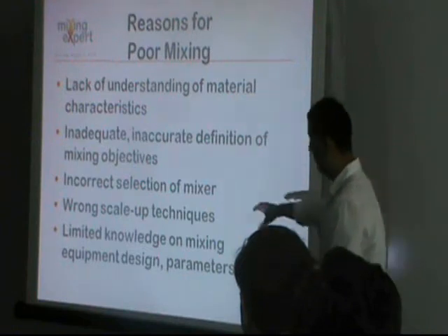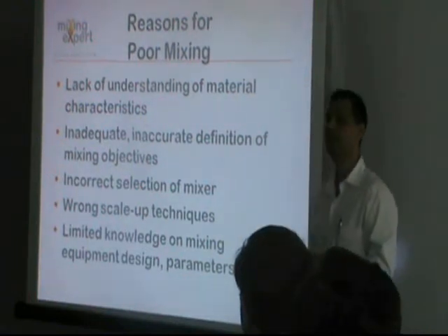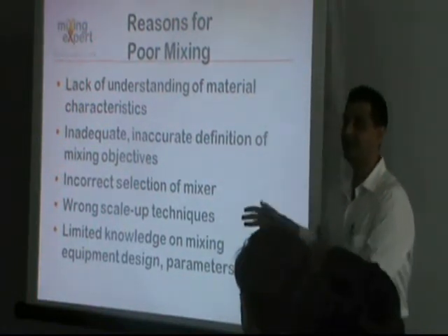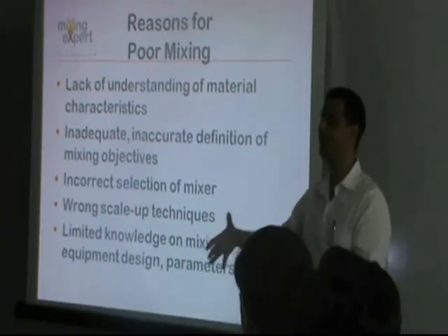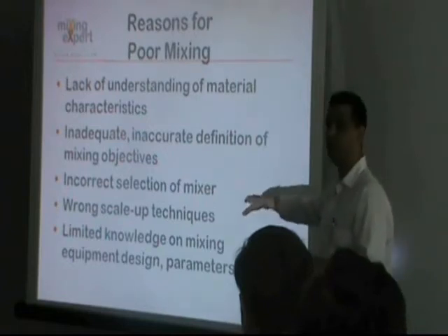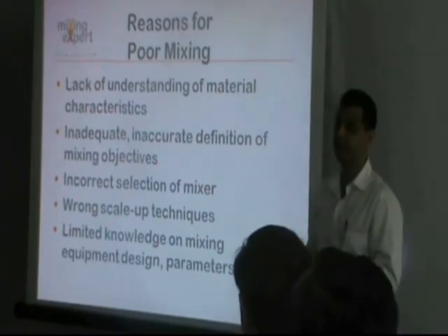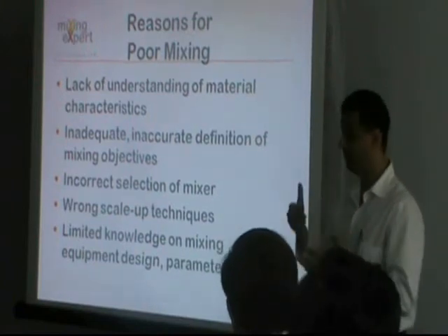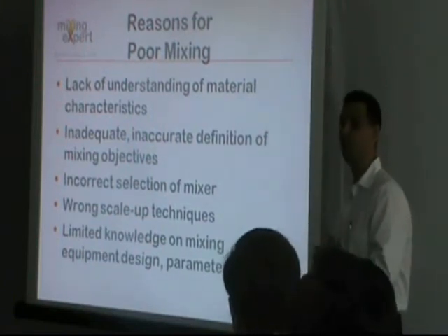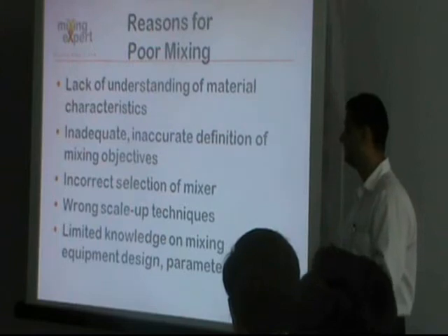A lot of times, incorrect selection of mixer. I mean, that's the tool. That's the tool which is going to convert your raw material into a finished product. It is very important that the selection of the mixer is done taking into consideration the material properties. We will look into what are the factors which get into the mixer selection.